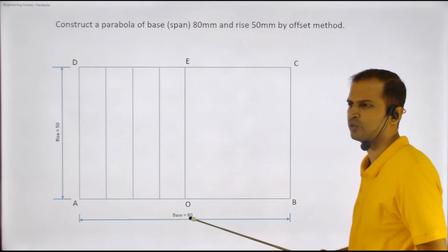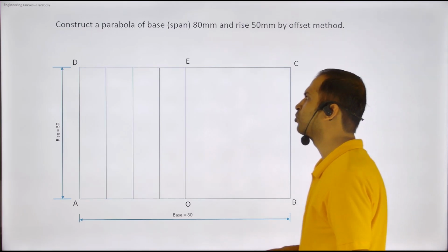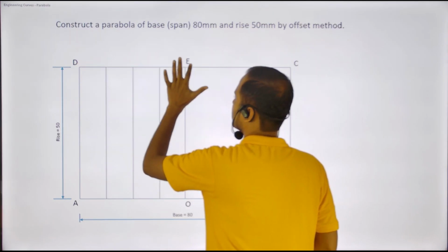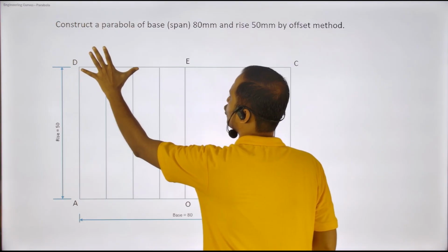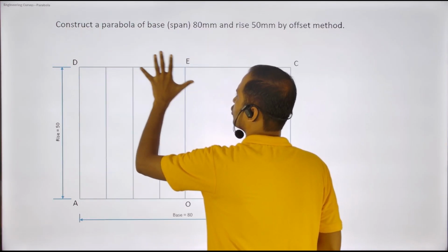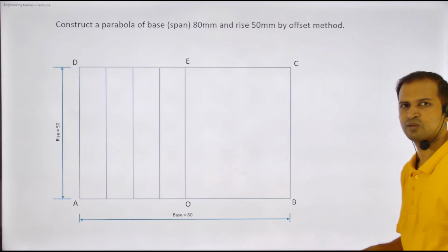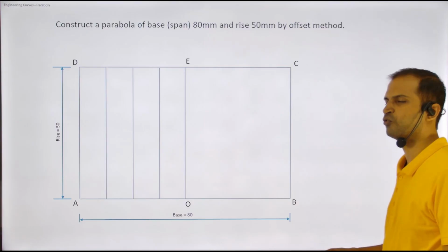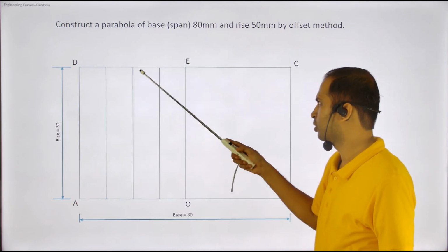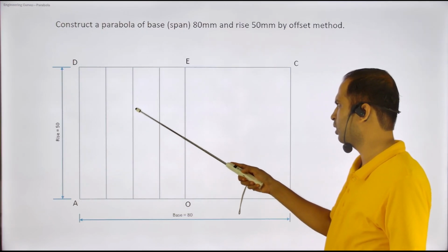So here now I've taken 4. Now observe carefully. This part is 1/4 of this whole line. This length is 2/4, meaning half of this length. This whole line is 3/4 of the total length, right? These are the calculations we are going to use: 1/4, 1/2, 3/4. And we're going to plot some points on this line, and then connect them and we're going to get a parabola.